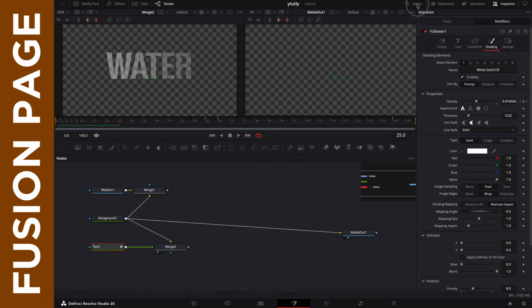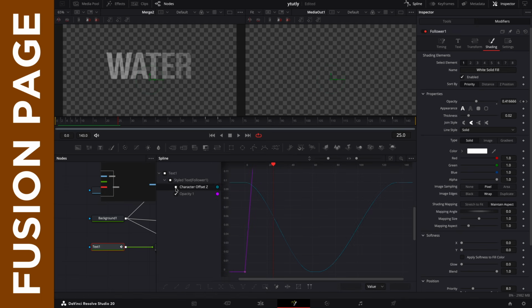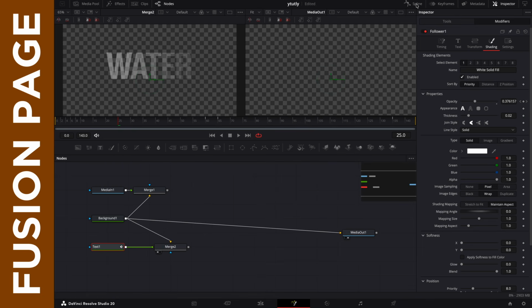Let's go to spline editor, uncheck character Z offset twice to make it disappear, then opacity shows, then click zoom to fit, then click on this, then click on this curve, and that's fine. Close the spline editor. Okay, so now we have this. Just the question now is, why am I not allowing it to fade out? You will notice that in the comp it has a particle wipe where it dissolves into bubbles and fades off. That's what we're going to do to make it wipe off.